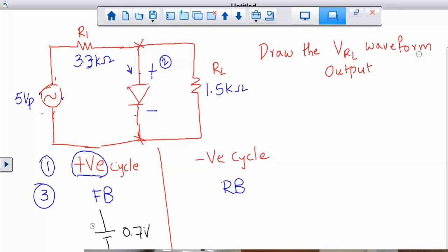So that means the voltage that you are looking at is positive 0.7. So the signal basically goes to positive 0.7. That's why it was above the time axis again. So let's say that's my axis. This is just the diode. I didn't draw the whole circuit, but you could draw the whole circuit, but that's just the diode.